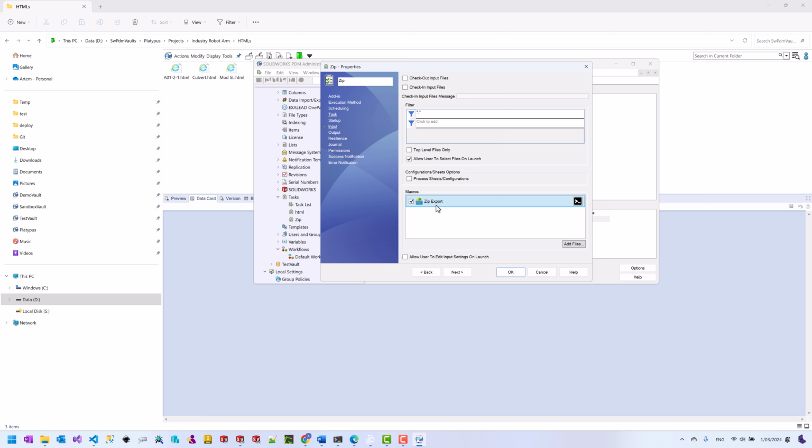This macro is in the vault, and it has several parameters. The first parameter is an output file for our zip archive, and we're going to put it into the root folder of the vault under the MFG subfolder, and we're going to name it after the common folder name for our input files. The consecutive parameters are the output types we want to include in our zip archive. It will produce a PDF file and a PNG file and zip them.